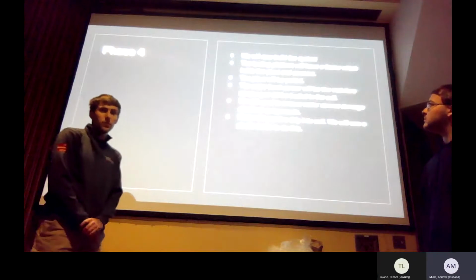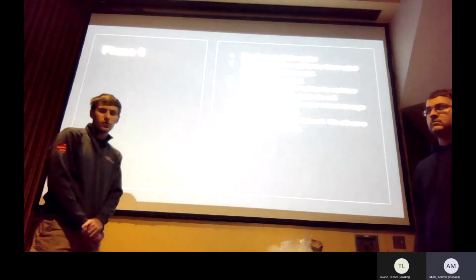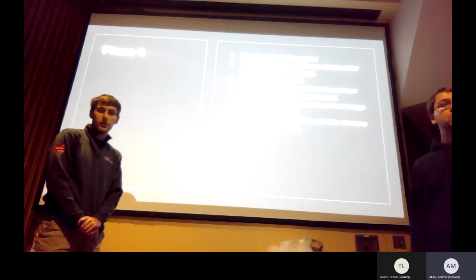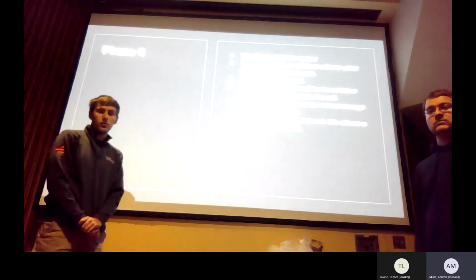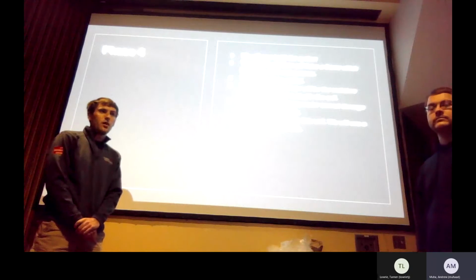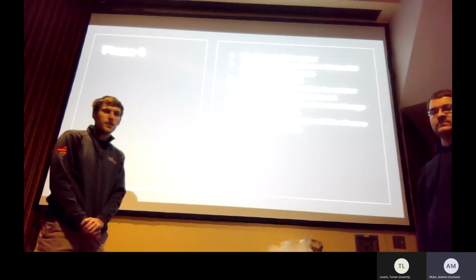Phase four is to build the system, and the first step in doing this is to build a test platform, which will have the water reservoir suspended above the plant specimen, and the soil moisture sensor in the soil. We need to ensure that the water cannot damage the electrical components, so proper care has to be taken to insulate those from getting wet.